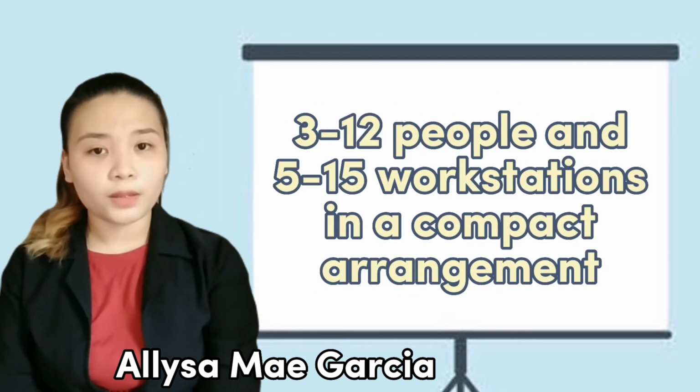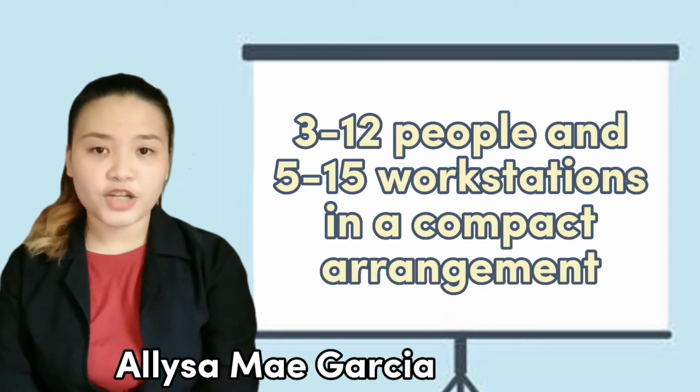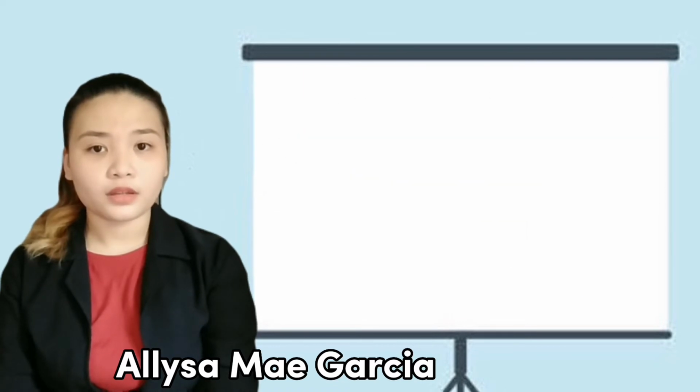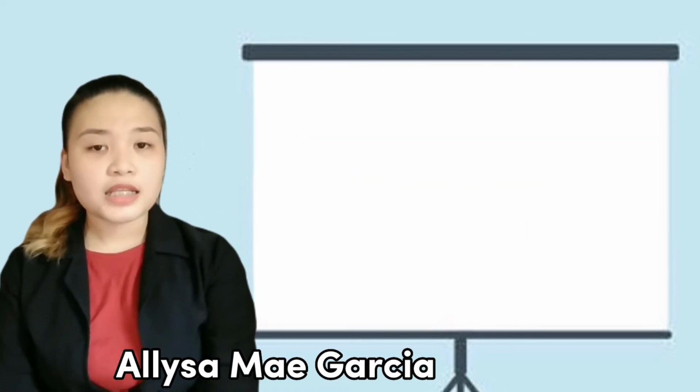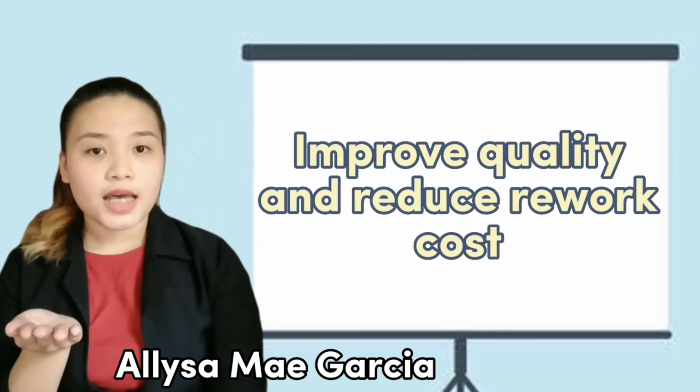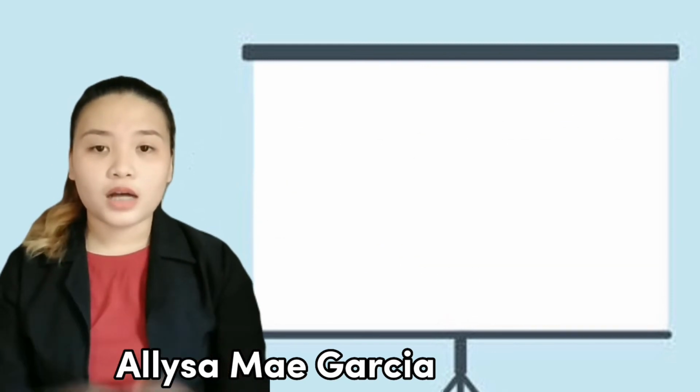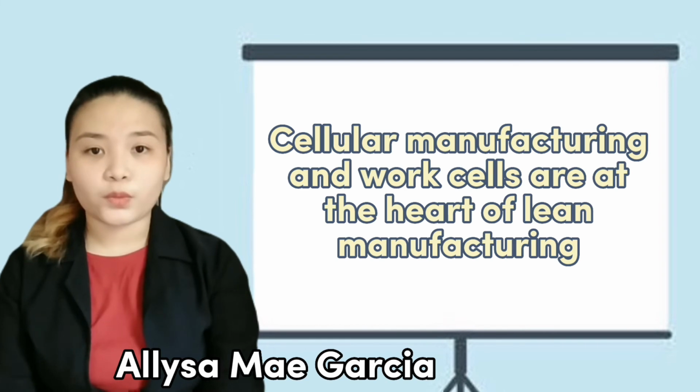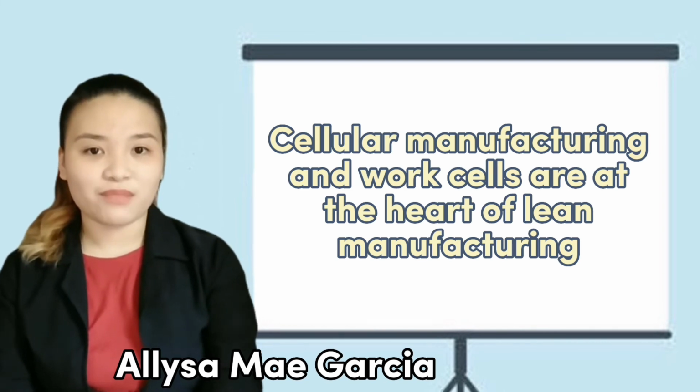The work cell is a work unit larger than an individual machine that employs 3 to 12 people and 5 to 15 workstations in a compact arrangement. Through cellular manufacturing, several advantages are seen such as improved quality and reduced rework costs. Thus, cellular manufacturing and work cells are at the heart of lean manufacturing.